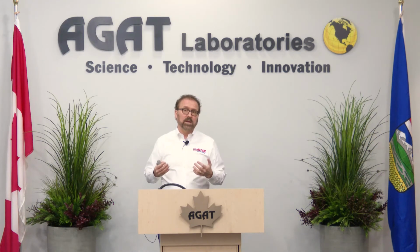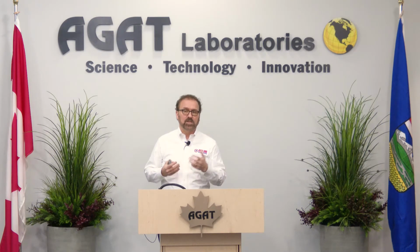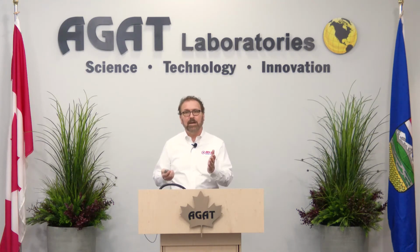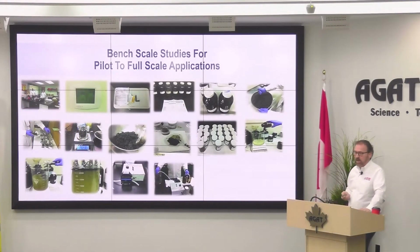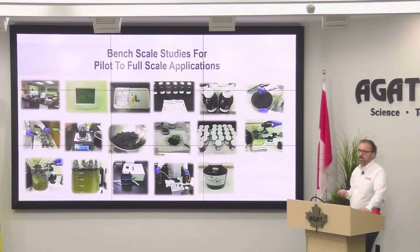In this case, we're doing 3 of these to establish baseline. How much is that free product getting in the groundwater? So we sample that and we get that value. Then we try 3 different dosages of the Ivey cell to see how much of that mass we can transfer in the aqueous phase for recovery by, in this case, our multi-phase extraction system. And then what we do after that test is use peristaltic pumps, as you're seeing here, for low flow sampling of the product into our jars for analysis.